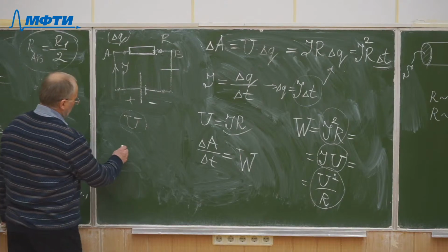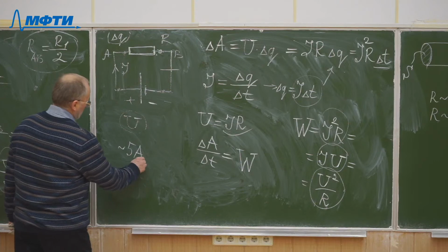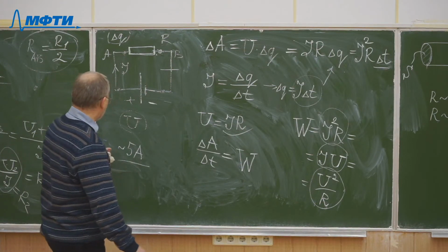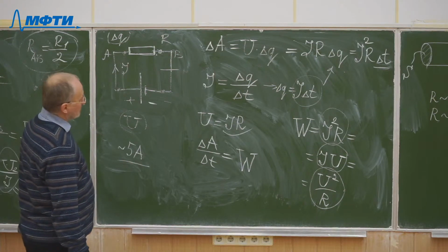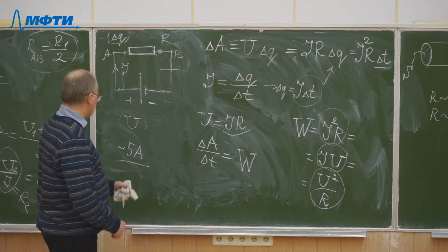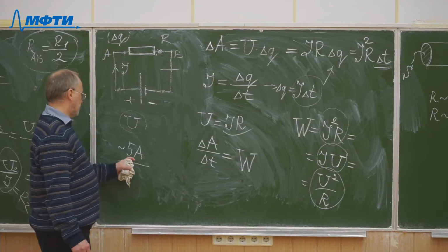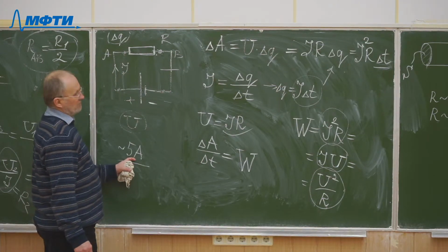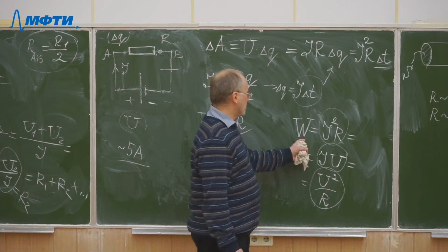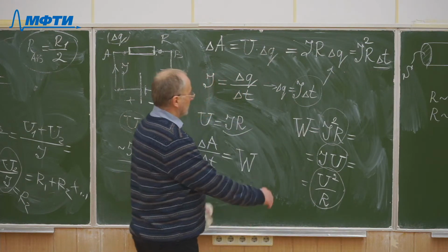If the fuse is only a 5 ampere fuse, it may be broken, it will be just burnt out and switch off your circuit if it's capable to carry only 5 ampere current, and you have switched on an electric heater and, for example, something else like an electric bulb, which takes about 60 watts.